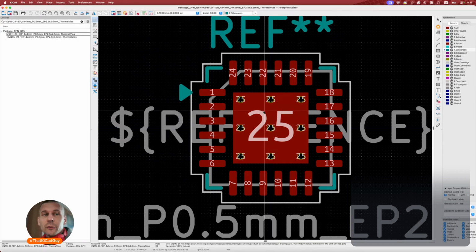So it's not optimal. It's not optimal because there is no reference plane next to each signal layer, because I think layer number 2, which is the first inner layer, was power, not ground. So it's suboptimal. A 6-layer PCB should be better, and I'm not sure if we will use the 6-layer or 4-layer. We will have to check the JLC PCB. I already did it, but I can't remember the numbers. But yeah, I will probably use the 6 layers.